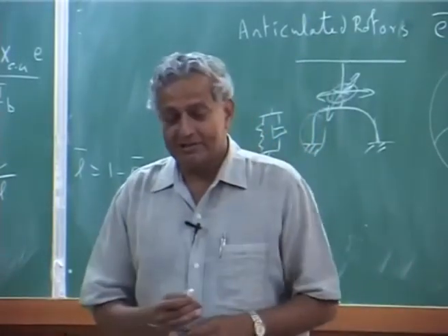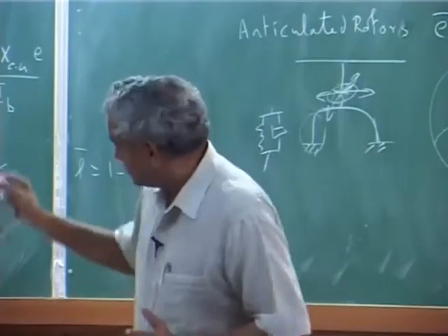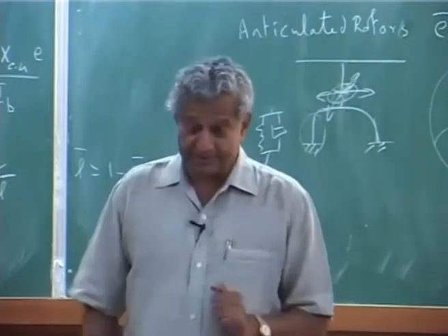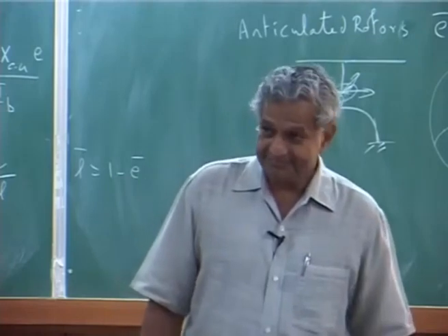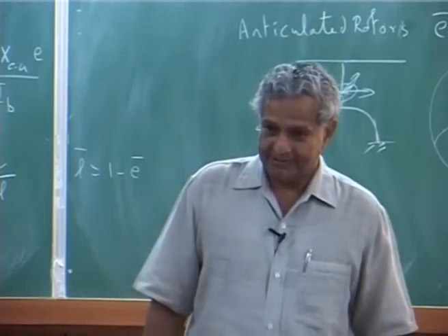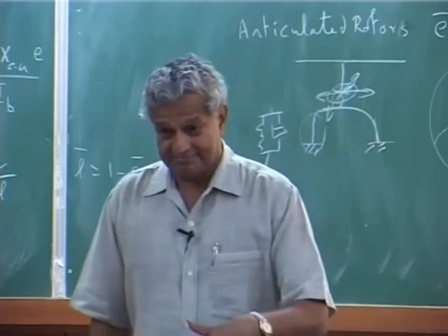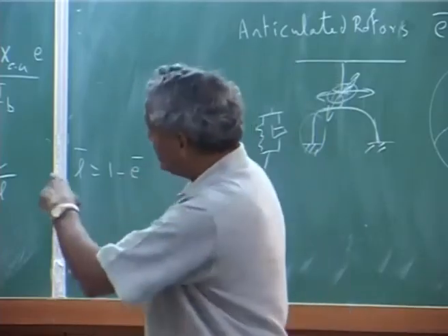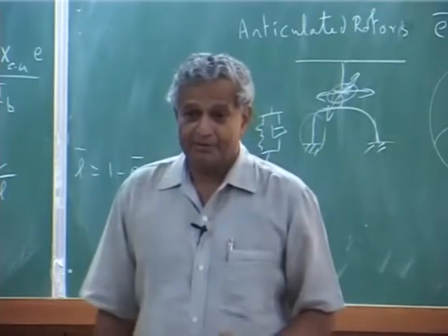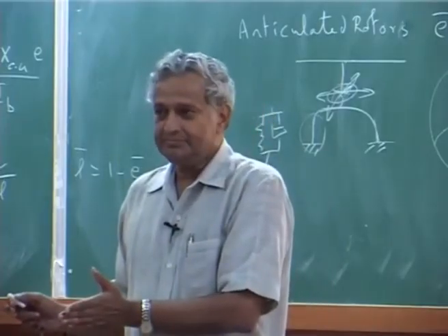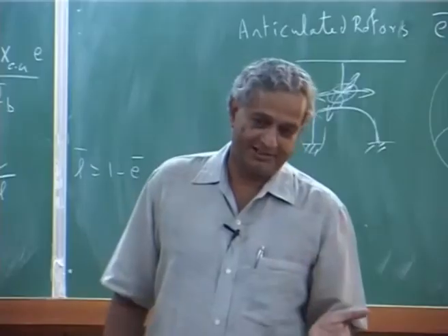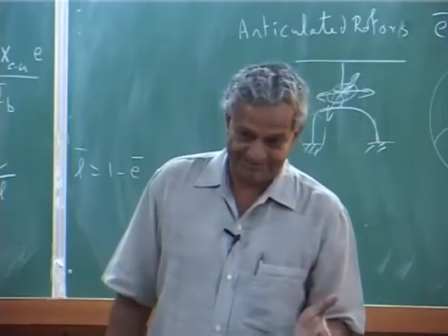Okay. But soft in plane, you avoid flap lag instability if you are far away, but you get into ground resonance, but the loads are less. Stiff in plane, far away, you avoid flap lag instability, but you have a high vibratory load.